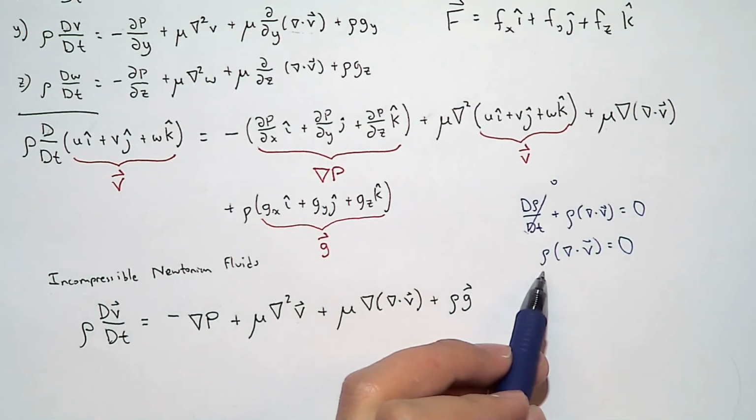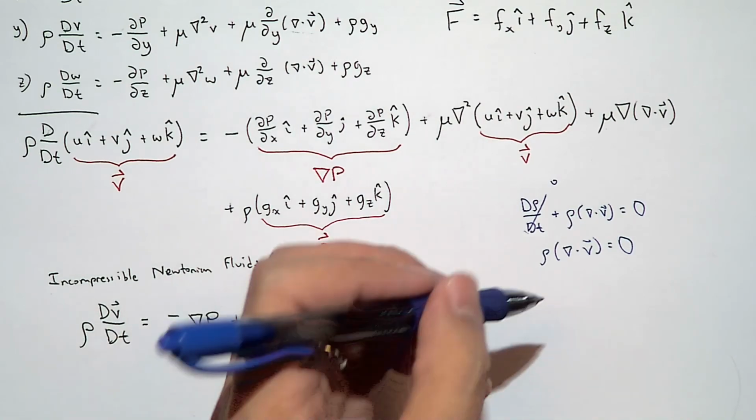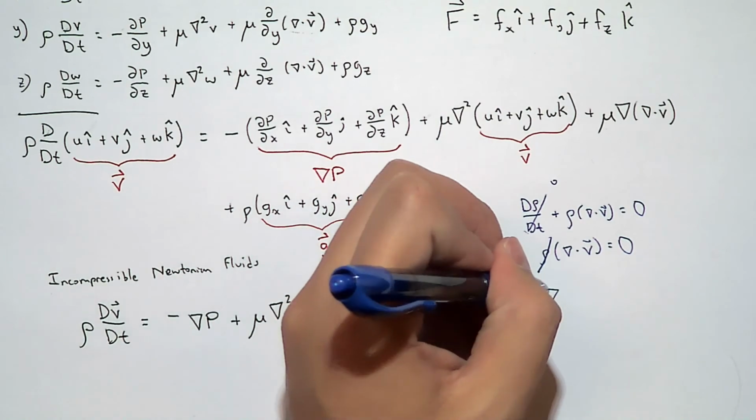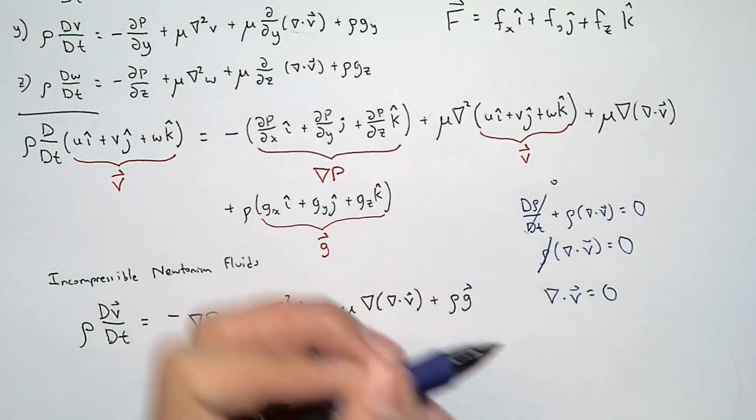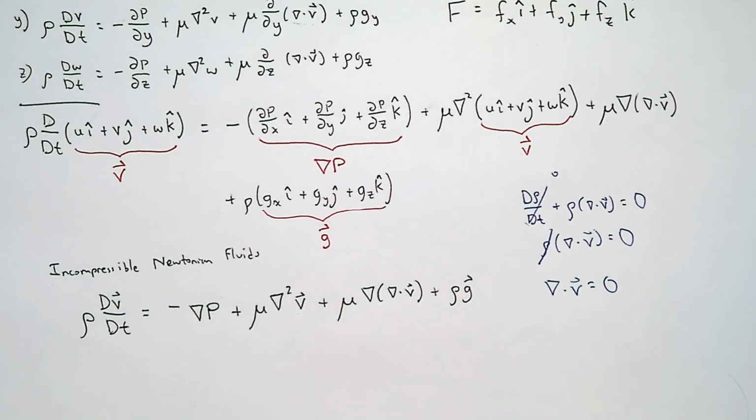If my fluid is incompressible, density is a constant. Can I factor it out? Eliminate it? So if my fluid is incompressible, we know that the dilatation rate has to be 0. So what can we do for this equation? Take out the part. Exactly.